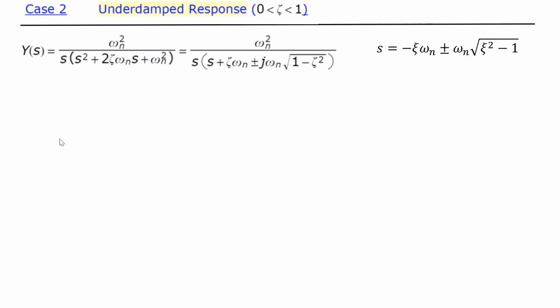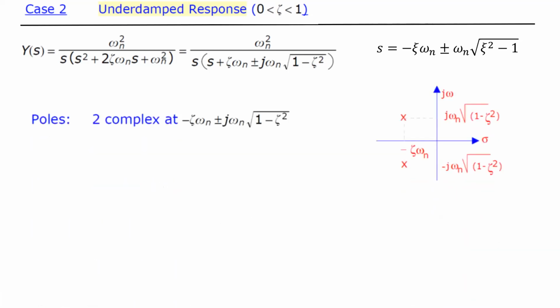If zeta is less than 0, it will be unstable, right? Yes, if zeta is negative, it will be unstable. The oscillations will expand. They will not decay. They will propagate more. Okay. So now, those are my poles. One is located here and the other here, and this on the real axis is equal to minus zeta omega n. So we'll have a kind of overshoot, and then it will...